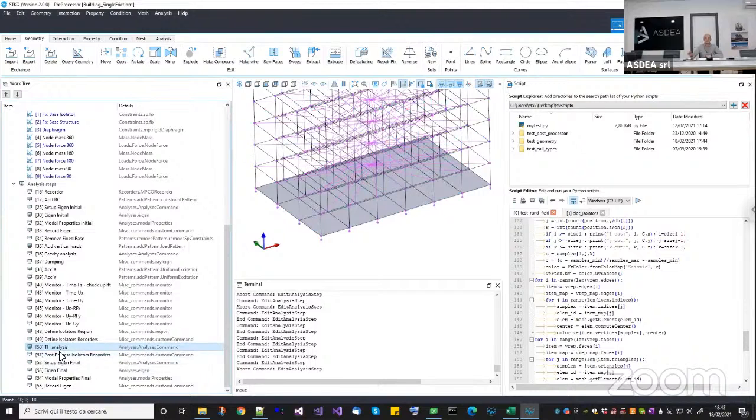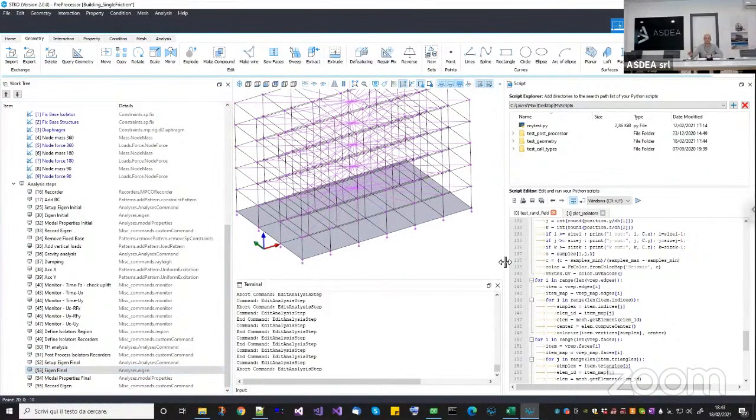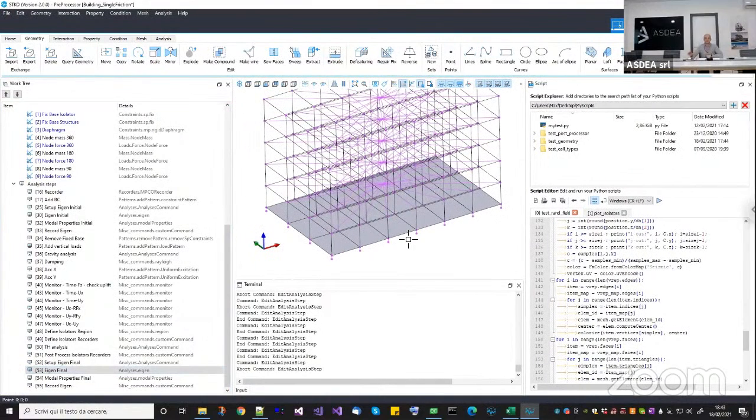If after the time history analysis your model goes into a nonlinear stage, the eigenvalue analysis will call the tangent matrix for every component. Now, the problem with the tangent matrix is that they do not always have a physical meaning, because the tangent matrix has a physical meaning only in linear elastic analysis, because it contains the constants of elasticity of your model.